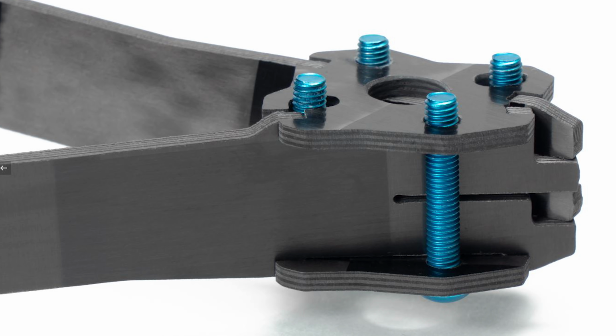But even if I still want to make things that interlock together, I'll still use a 2 millimeter radius for the interlocking part. And I'll have to make these weird U shapes and I shapes and whatever to get the parts to actually fit into one another with the processing that I'm using. Now, you guys are using a water jet so that you can literally cut a 90-degree corner in the carbon fiber. And that means that when you have a square piece that's slotting into another square hole, it actually fits into each other and you get intimate contact between all surfaces of the hole and the piece that's fitting into it, and you don't have these extra spaces that you have to make just to get the carbon pieces to fit together and interlock, right?